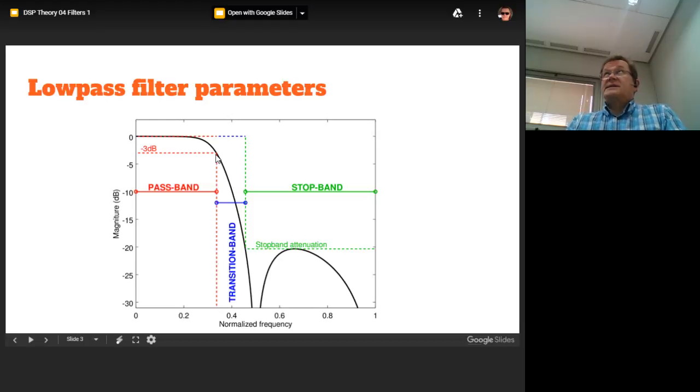On analog filters, it's quite usual that we define the cutoff at the -3 dB point, but it can also be defined by some other attenuation point. So if we have a filter which has ripple on the passband, usually the level of ripple is actually defined as the cut-off frequency. So just a reminder that it's not always like that.